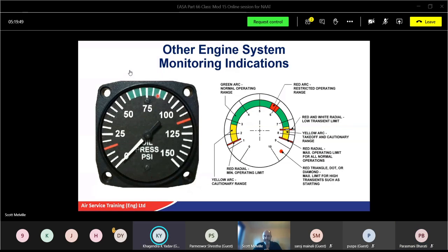Yes. Thank you. If you're setting your index on your DPI gauge, you might have to adjust for if you've got a certain thing switched on or off. What might affect the thrust indication switched on or off? Anti-icing. Yeah, anti-icing, because that's going to affect your thrust.